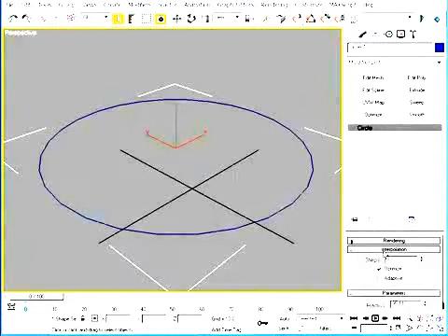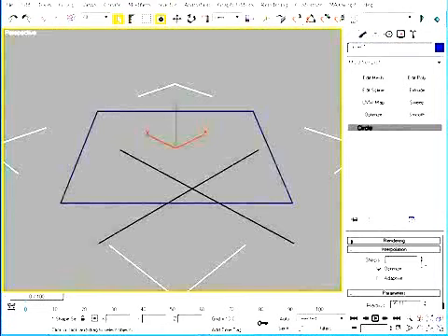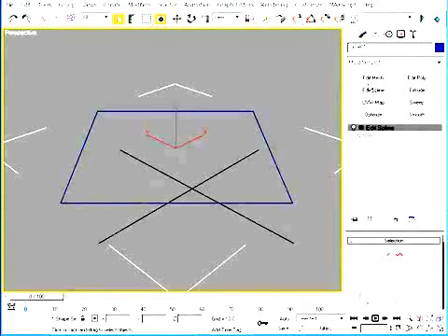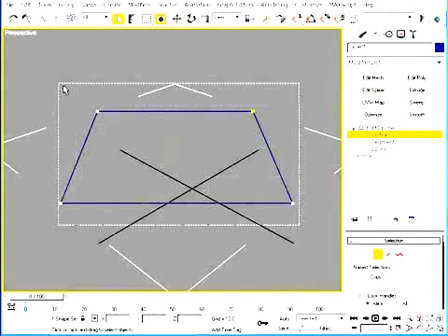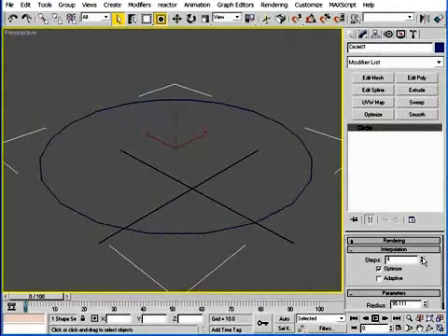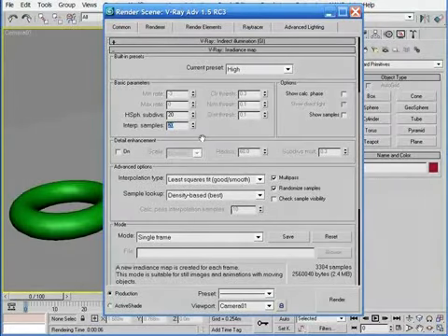We can look at this in a very simplistic form by just looking at a simple circle. Now, when you create a circle, 4 vertices are created in that circle automatically, but there is an interpolation rollout with the circle that allows you to reduce the interpolation value from 6, which is the default value, to 0. When you do, you'll see that the circle becomes a diamond, and that's because there's no interpolation, there's no guessing between those known vertices. So if we increase the interpolation, we are increasing the number of steps, number of guesses or estimations in between the known values. And the same thing is happening within the irradiance map. The interpolation samples value determines how many of the irradiance map samples that were taken will be used to estimate the GI between those samples.